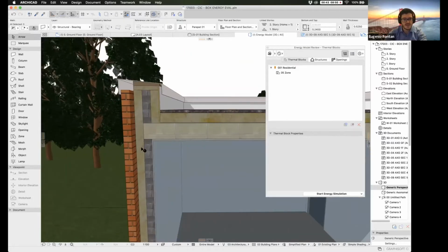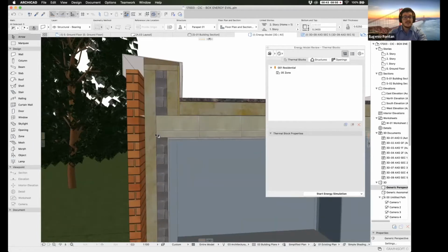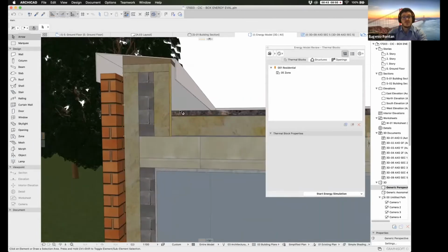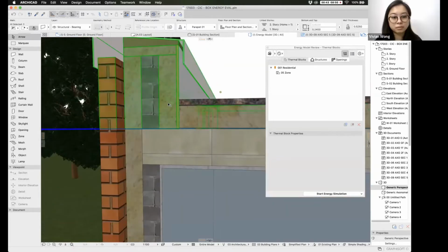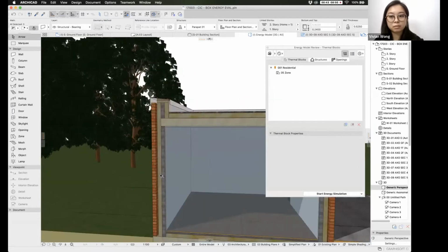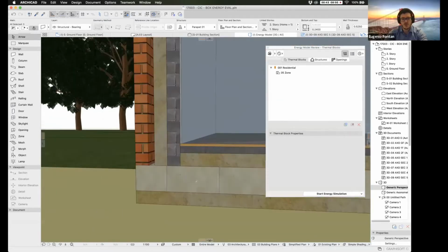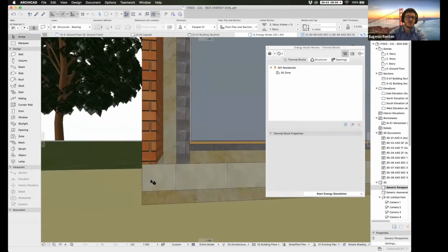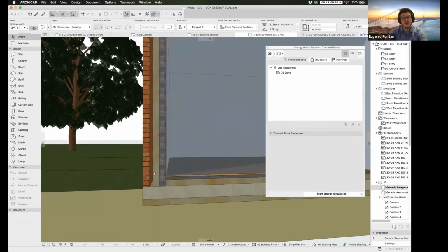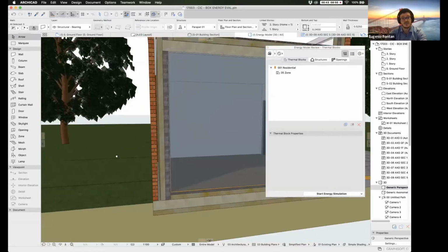So all the building materials are connecting between each other, but just as a note, if we develop this further, here we have this finish going through this insulation layer, which is not good. We'll have to work that out. We could also optimize the way we have this insulated because we have some cold bridge, some temperature bridge, where the insulation is not continuous. So we could work out this detail a bit, and all that will influence the energy analysis of our project.